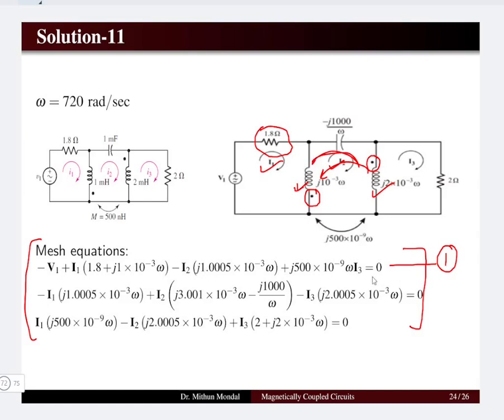We have to take into account the voltage drop due to the reactances. So we have to individually write equations 1, 2 and 3, which are the KVL equations for loops 1, 2 and 3, where clockwise direction of the current is assumed. Appropriately we have to take the direction of the voltage drop.